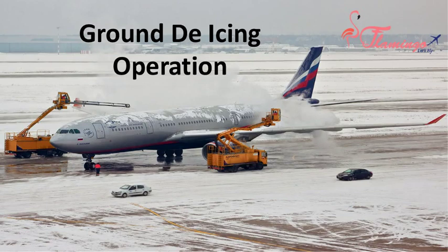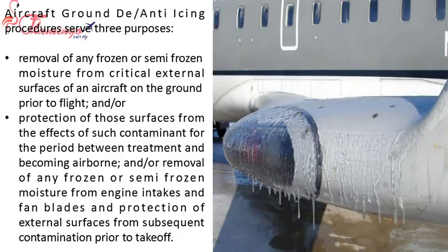Today we will study about ground de-icing operation. Aircraft ground anti-icing procedures serve three purposes: removal of any frozen or semi-frozen moisture from critical external surfaces of an aircraft on the ground prior to flight, and/or protection of those surfaces from the effects of such contaminant for the period between treatment and becoming airborne, and/or removal of any frozen or semi-frozen moisture from engine intakes and fan blades, and protection of external surfaces from subsequent contamination prior to takeoff.